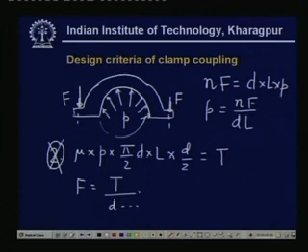So, from this, when you substitute P here, you get F in terms of T, d, etc. So, you get everything in terms of T, and F is the bolt area times the allowable stress, that is the allowable force, the maximum force available. From this we calculate the bolt diameter by looking up the table.